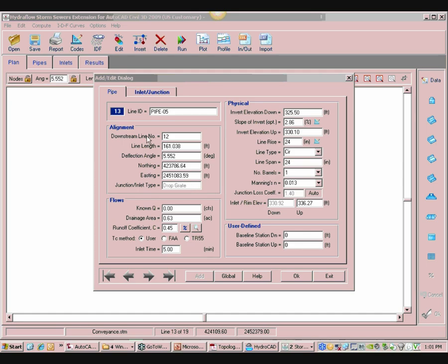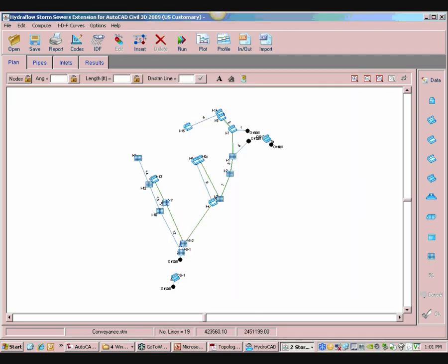Does it import the structure type? No. Well, yeah. What do you mean, Jason? Jason Lutz asked, does it import the structure type, when you take the information from Civil 3D into HydroFlow? No, it doesn't. They're all manholes. Sometimes, depending on the structures, it will designate if they're inlets or manholes, but most of the time you have to set it up. But you just have to set it up once. Once you set it up once, you use that utility to round trip the data, and Brandon's worksheet does, I churn these all from manholes into generic grates or whatnot, and it brought that back across.